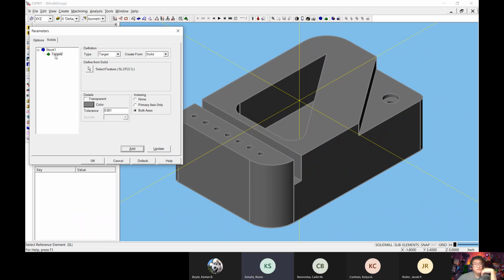I don't know how you're getting target. You don't see target? No. You can click on this minus thing over here. It might have disappeared. No, there's no minus thing there. Before you add the target, you should have stock highlighted so it knows what to add it to. Should I add the block first, right? Yes, add the block first, and the block is your stock.